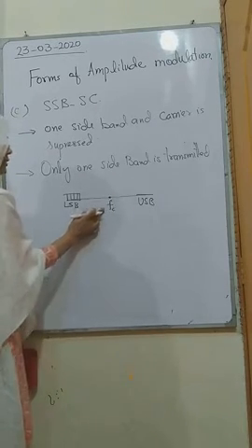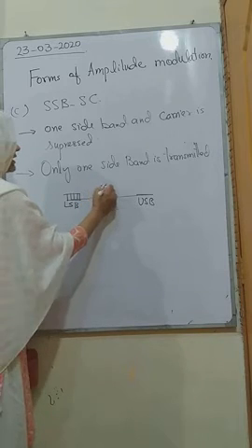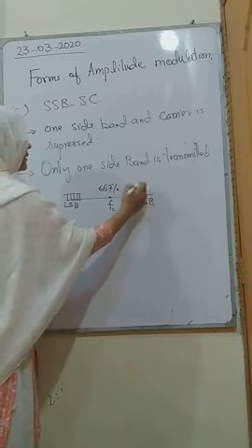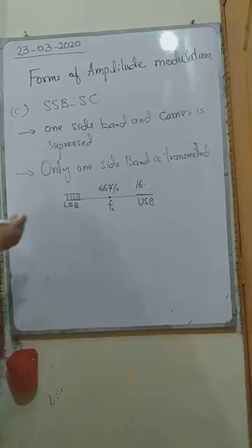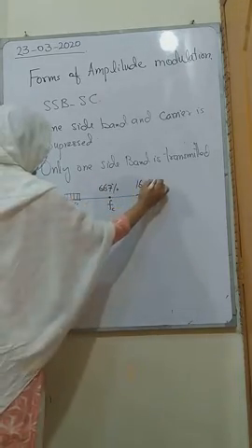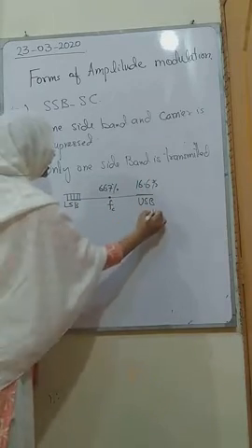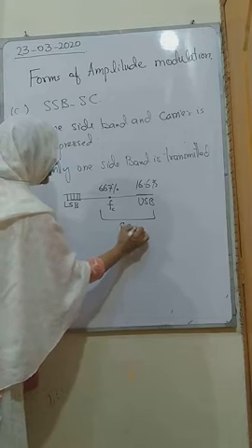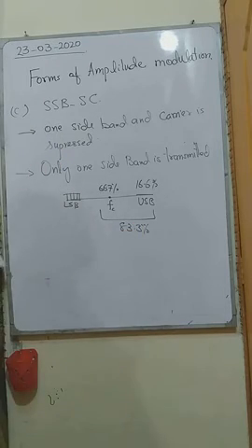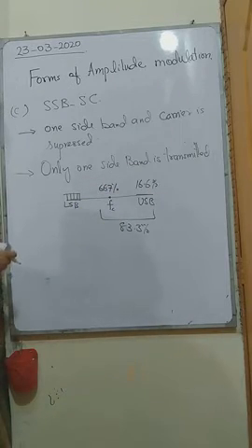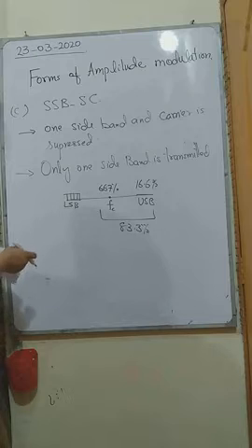The power consumed by the carrier is 66.7% and by the sideband is 16.6%. So by suppressing these components, we save 83.3% of the power of the modulated wave. You can see that by suppression we can save a lot of power.